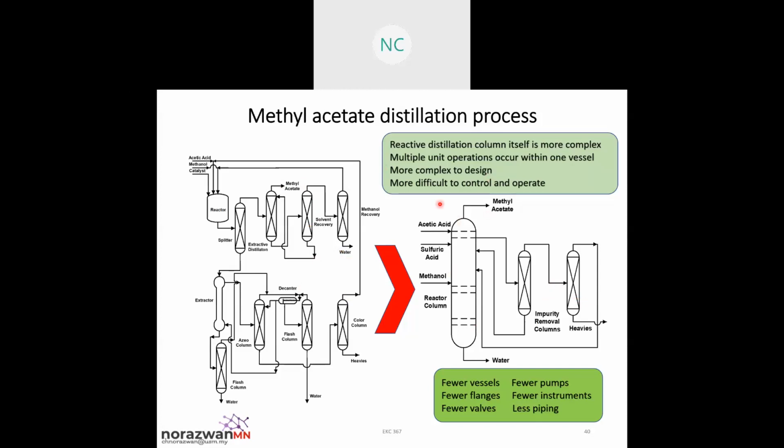Even though this looks simple, it will be complex to design because it involves difficult control and operating conditions. This extraction column will depend a lot more on operating conditions, on how you try to eliminate or extract all this material. All this depends on your operating conditions, because the distillation process itself is temperature dependent, and depends on your pressure and temperature.